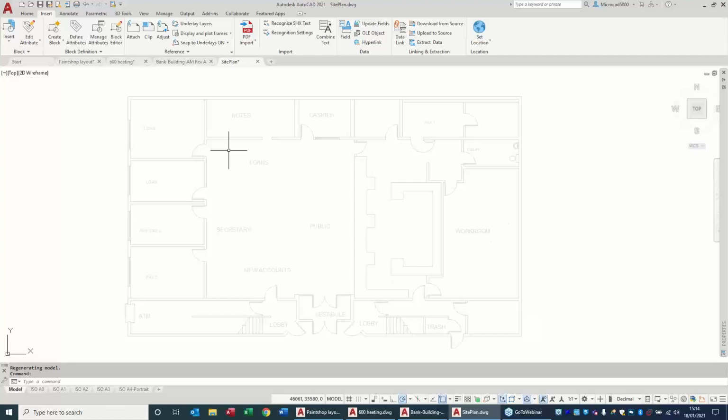Okay. Now, before you issue the drawing file, what you need to do, because you don't want your issued site plan updating when the architect sends you a new floor plan, or when the guy down the office updates his drawing file, the floor plan drawing. There's always a danger of that. So your issued drawing file would end up getting changed. And that's a bit dangerous. So this is what you need to do.